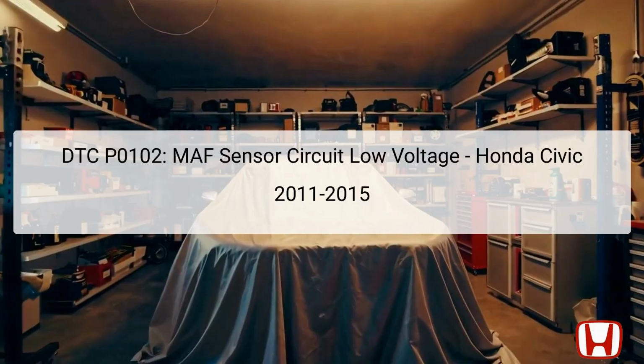Diagnostic Trouble Code, DTC P0102, indicates a low voltage issue in the mass airflow MAF sensor circuit. The MAF sensor measures the amount of air entering the engine, which is crucial for the engine control module, ECM, to calculate the optimal fuel-to-air ratio. Located in the intake air duct, it can be prone to issues such as wiring problems or sensor failure.